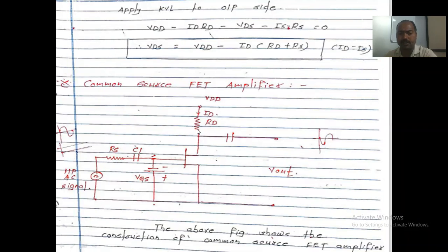So this does not drop any voltage. Okay, so whatever voltage is coming across here, all of that voltage is coming across your output. That's why this 6 is coming across here. So this positive going voltage appears across here. The only thing with respect to this type of configuration is that whatever voltage is applied across it should be dropped by this resistance.